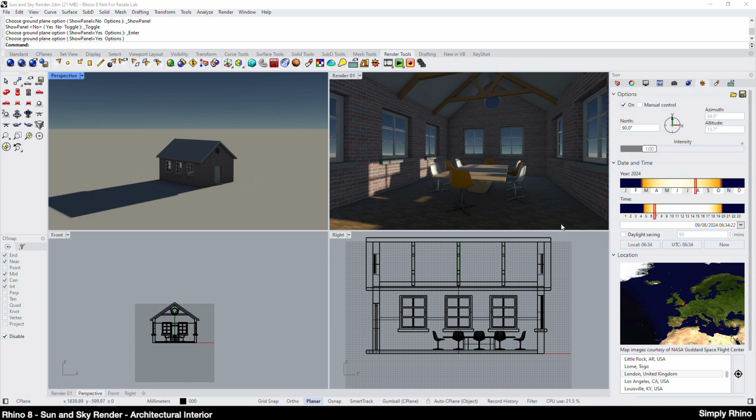Looking now at the interior viewport, I've now set the time of day to produce some interesting lighting in my scene. And to show more detail, I really need to switch the display mode to Raytraced. Before I do this, I should explain that with an interior scene, I'll get significantly better results by creating an offline render than I'll see in the Raytraced viewport.